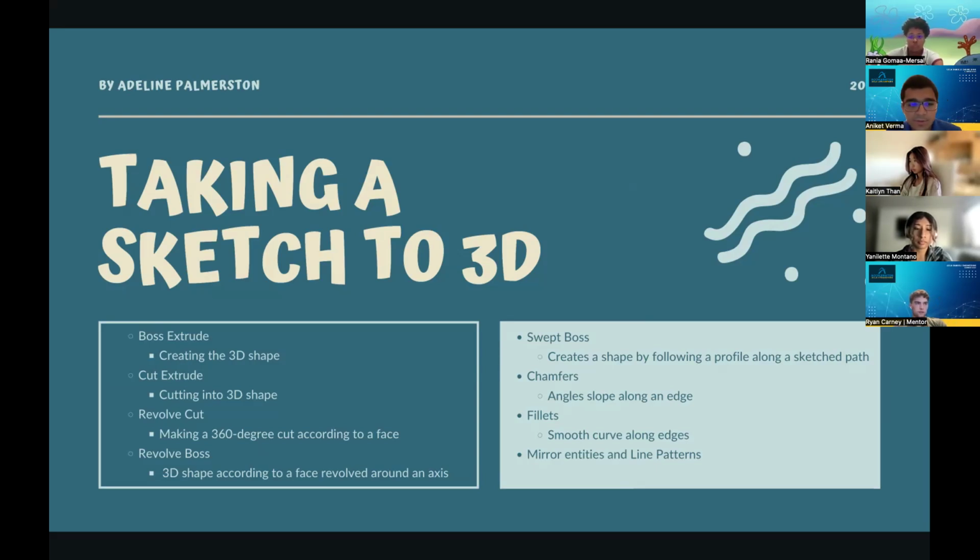Sweeping, and yeah, so basically a sweep, you can think of it as extruding something along a path. So when I sweep something, I have to define two different sweep points, or like two different sweep faces, and then a path along those two faces which I want to sweep on, and that'll help you create an extrusion of that. I'll demonstrate all of this, so don't worry about any of this right now.